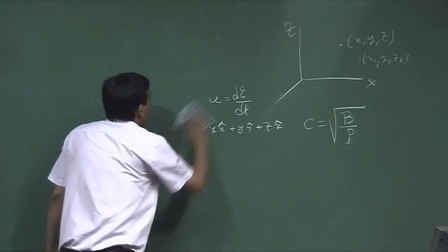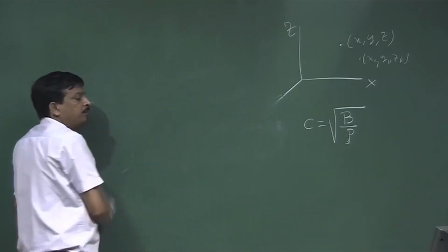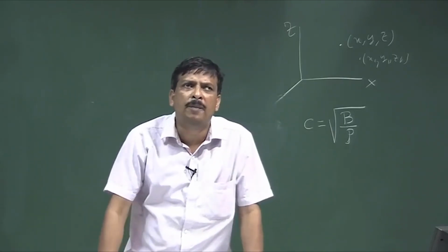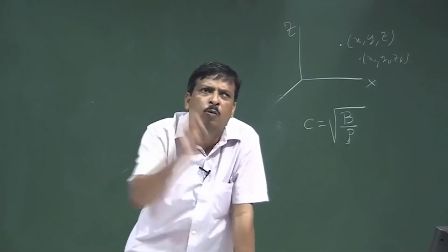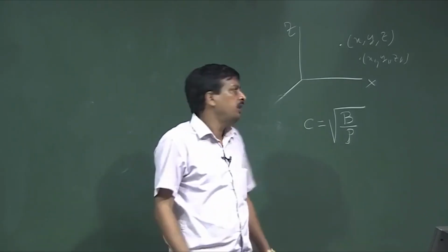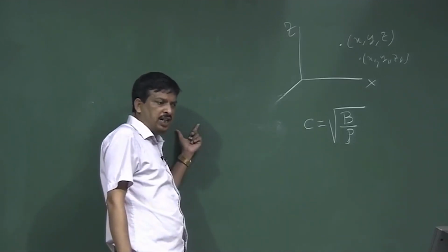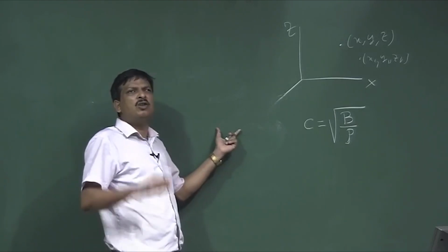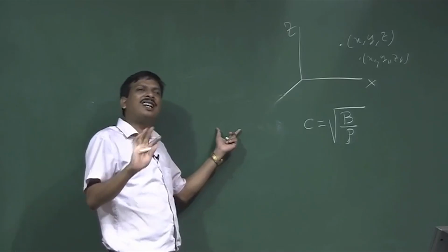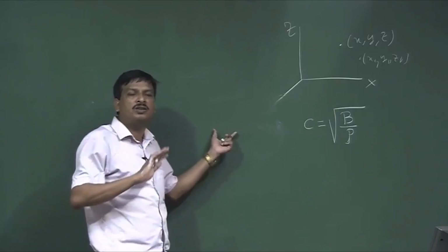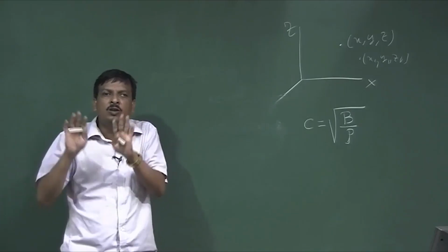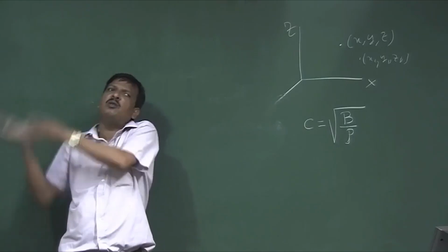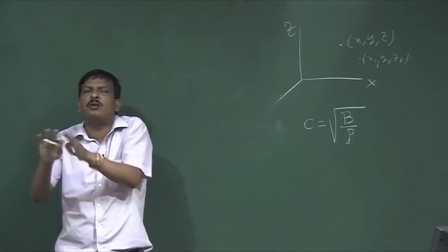We said when sound is propagated in a medium, the medium does not change, and the equilibrium density of the medium at all points is the same. So, that means the medium is homogeneous, isotropic and an ideal fluid. Ideal fluid means there is no viscous loss, there is no friction loss. In practice it is not so, but simply we put those constraints to derive that equation, then we employ one after another constraint to see how the equation is modified.